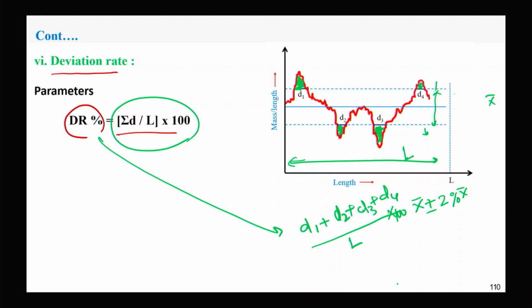So these portions of the yarn will be thinner and other portions will be thicker. So this will give one numerical value, which will represent the visual appearance. The higher this DR percent, that means deviation rate percent, it will give us the indication that okay, this particular yarn is giving some higher thick thin places or higher variability. So DR means deviation rate. Okay.